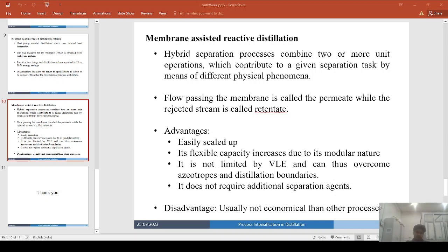Now, what are the advantages of high G? The HETP values in high G are as low as about 2 to 8 centimeters. So that is quite a very advantageous value. And there is a volume reduction of a factor of 4 to 7 for certain distillations as compared to classic columns.